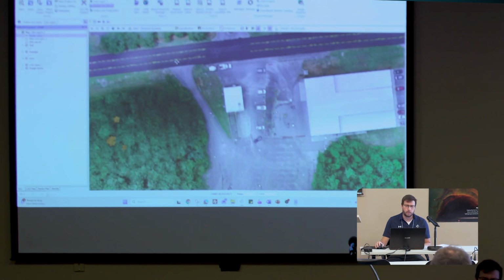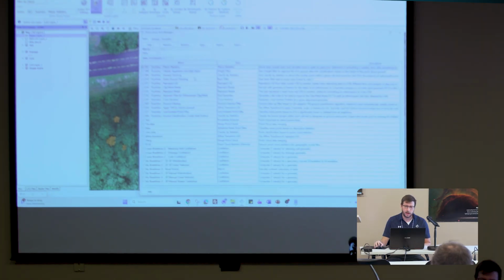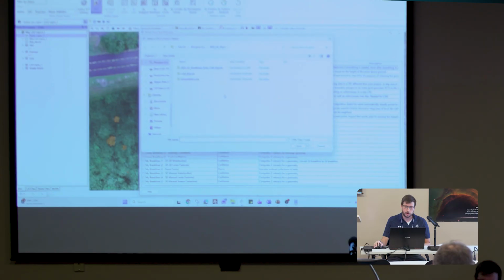So one of the things I've given you for this exercise: go to Point Task at the top, go to PCT Manager here in the top left, and click Import at the top, and then navigate to the PCT Groups folder from the exercise data, and then click on the 2025 UC CAD export group.